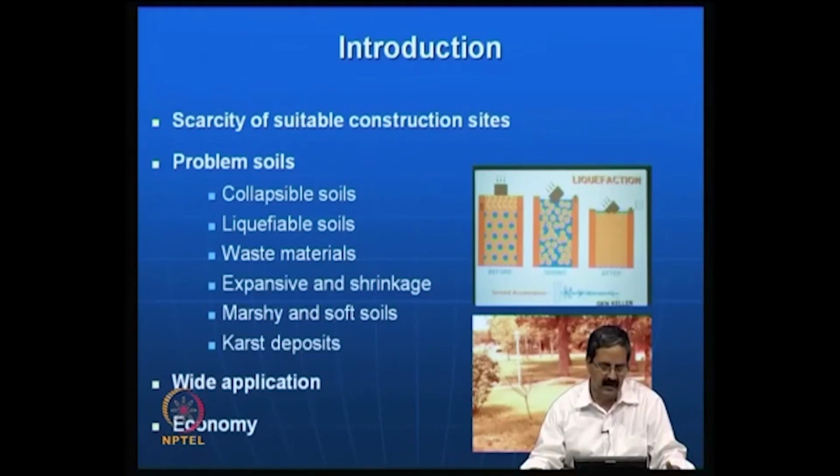Liquefiable soils are essentially sandy soils, which have a tendency for liquefaction, meaning they behave like a liquid under the influence of impact loading like an earthquake. Before an earthquake occurs, and then during the earthquake event, which is about 30 seconds to 1 minute, there is a particle rearrangement, and the foundation that you have at the top could sink in.